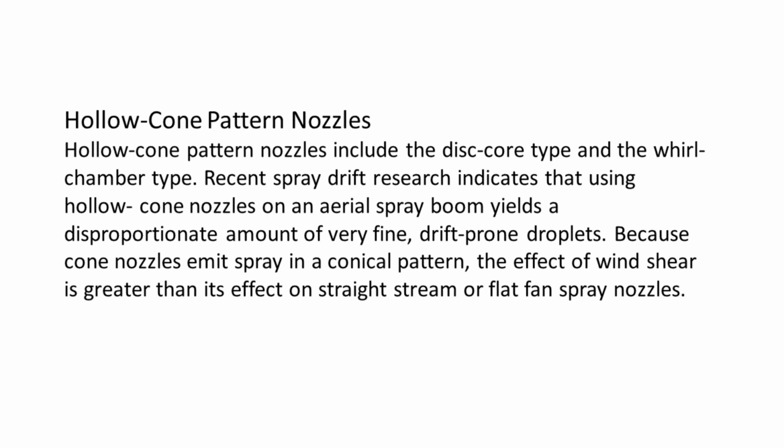Hollow cone pattern nozzles. Hollow cone pattern nozzles include the disc core type and the whirl chamber type. Recent spray drift research indicates that using hollow cone nozzles on an aerial spray boom yields a disproportionate amount of very fine, drift-prone droplets.